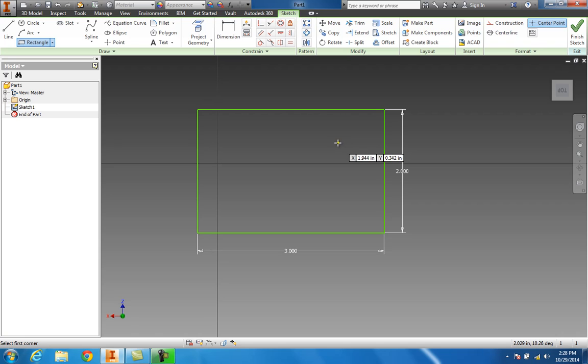And it looks like we've got 4 holes in this thing. We just got to find out exactly where they're located. I'll put those in, but I'll have to find out what the dimensions are on those first. Okay, they are 1/4 inch in diameter, and they're 1/2 inch off. So I'm just going to put one right here.